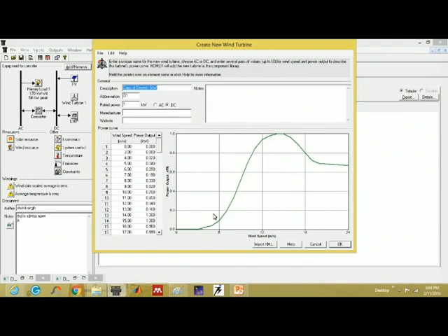The mathematical concept remains the same. There is a formula to find the power from a wind turbine. If wind speed is less than the cut-in speed, there is no power. Between cut-in speed and rated speed, power goes according to the velocity cubed. Between rated speed and cutout speed, rated power is generated. If wind speed is greater than the cutout speed, no power is generated. That is how we calculate it, and we can even verify things mathematically.